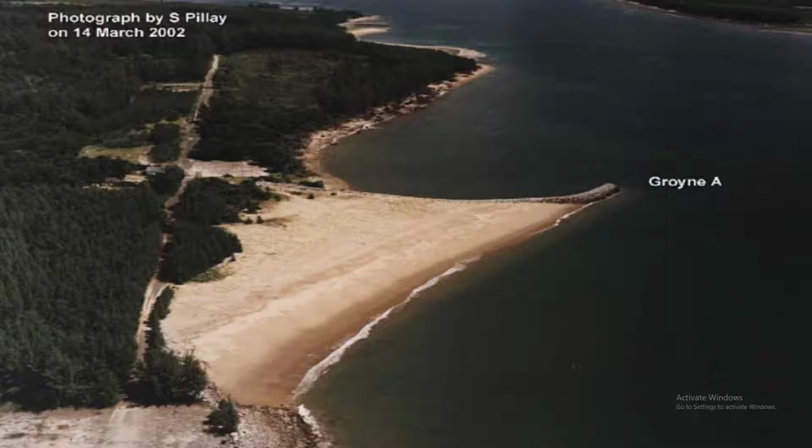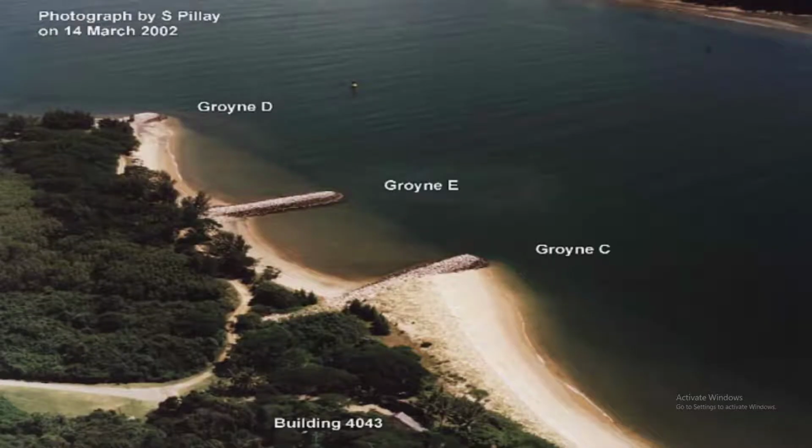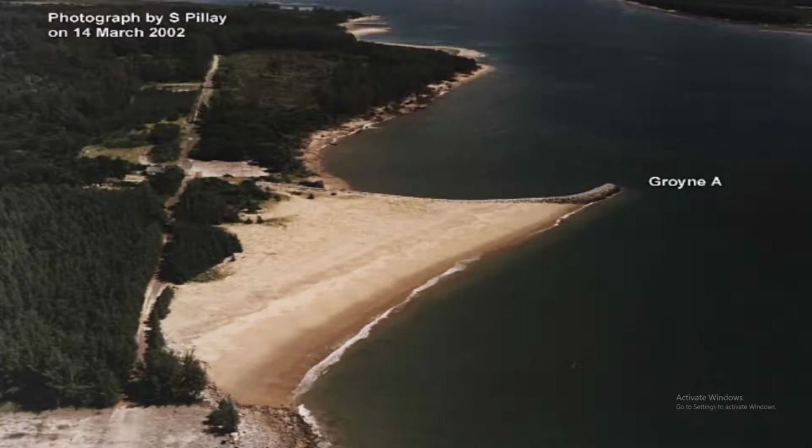In this case, the results showed a positive accretion and stabilization of the shoreline. Groins A and C, pictured here, saw rates of accumulation varying between 0.025 and 0.065 meters per day. Shoreline erosion did occur behind groin A, but this is to be expected and helps with shoreline stabilization. Equilibrium between the two groins is expected to be met within 3 to 4 years after the project. This example shows the positive effect of correctly using groins.